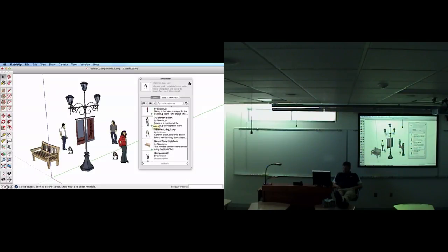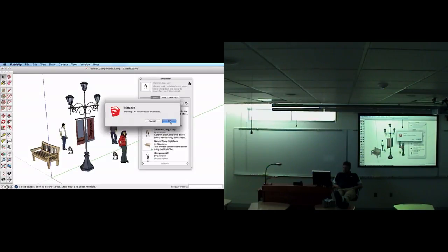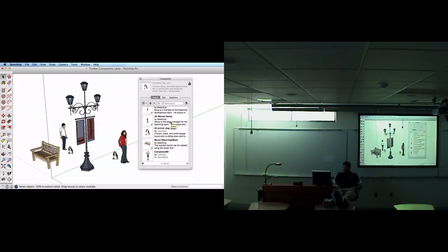If you wish to also delete them from the component browser in Model List, you can right-click on a component icon and choose Delete. This will delete any instances in your model that remain as well. A quick way to delete multiple components from the in-model view that have been deleted from your scene is to click this flyout menu and choose Purge Unused.